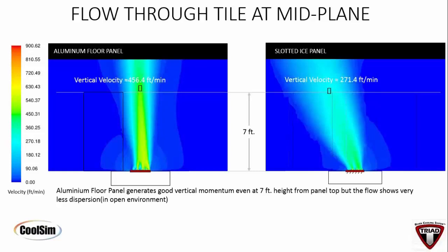Now on that, Paul, there's a terminology out there now about capture. One of the myths is that there's a boundary layer right at the face of the rack. It's created by two things, the heat and the rack door itself, the screen mesh that we see there. Air and water do the same thing. They take the path of least resistance. When it's running up to this boundary layer, the heat layer, which is kind of like a wall effect, or a screen mesh that has small porous holes, the air is going to want to go to the largest cavity. It will bounce away.